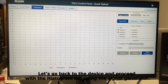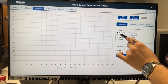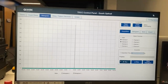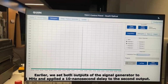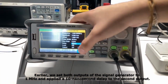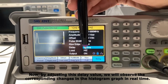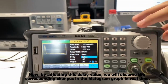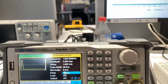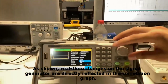Let's go back to the device and proceed with the histogram tab using the signal generator. I selected my channels and pressed the Run button. Earlier, we set both outputs of the signal generator to 1 MHz and applied a 10 nanosecond delay to the second output. Now, by adjusting this delay value, we will observe the corresponding changes in the histogram graph in real time. As shown, real-time changes on the signal generator are directly reflected in the correlation graph.